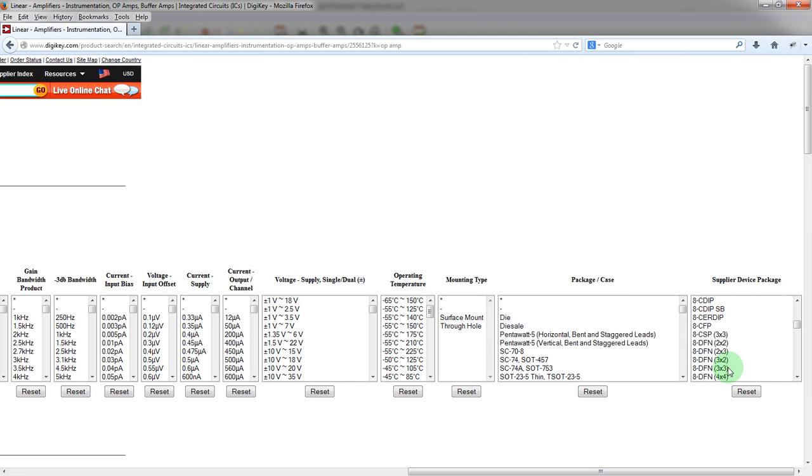The other thing we're going to be looking for here is the fact that it actually has a footprint inside the PDF, just in the main datasheet PDF, because sometimes vendors put these off in separate documents and you can go find them, but that's just a little boring and tough to find sometimes. I want to try and make sure we see something odd. You can see a lot of these are non-standard parts. Not non-standard, but just a little bit less common.